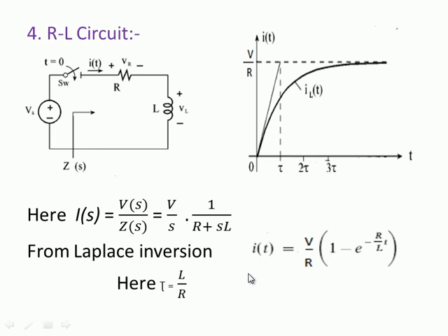The larger the value of inductance as compared to resistance, the slower will be the build up of current in this circuit. That will be just like this, just below this, slower, because the more the inductance, the more it opposes the change in current. It means the higher the value of this as compared to this, the slower will be the rise in current.